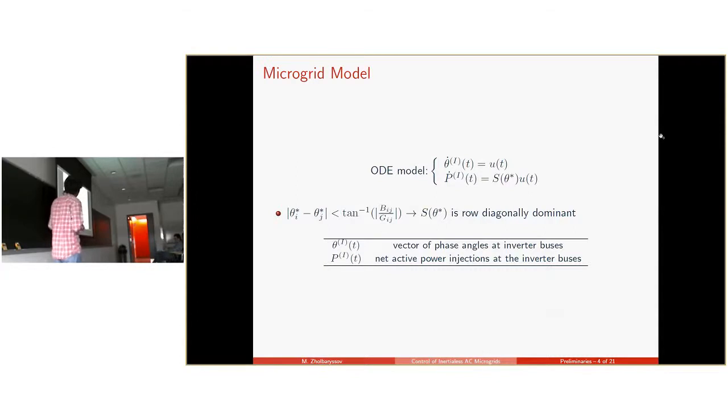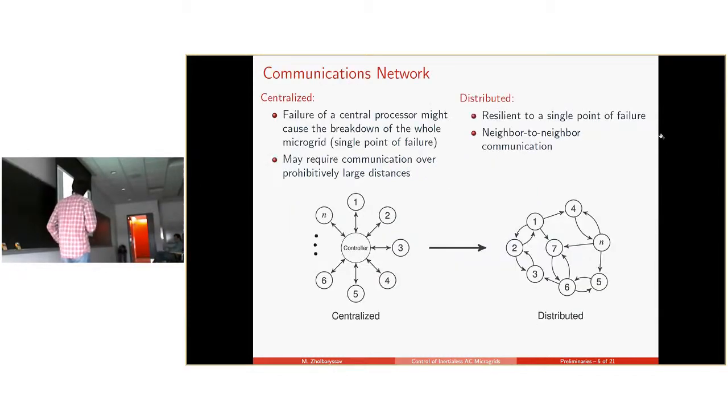the loads and fixing the voltages, we obtain this ODE model, which is a very simple relationship between the inverter injections and the frequencies. And matrix S at the equilibrium point has some nice properties if the phase angle difference across each line is bounded by some bounds, which depend on the line susceptances and conductances. So we're going to use this model throughout this work.